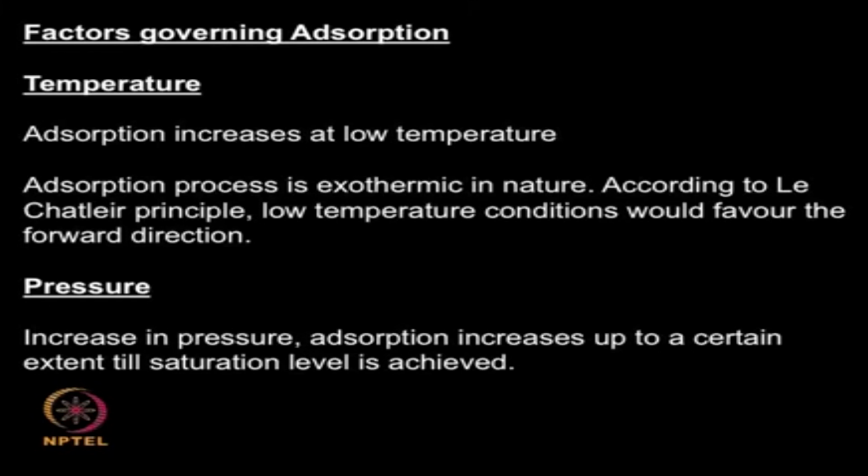At low pressures, an increase in pressure increases adsorption until the whole system reaches a saturation level, and after that the pressure has no effect on the adsorption process. So pressure also plays a very important role, especially in gas solid processes, where pressure is extremely crucial, whereas in liquid solid processes pressure is not so crucial, whereas temperature will play a very crucial part.